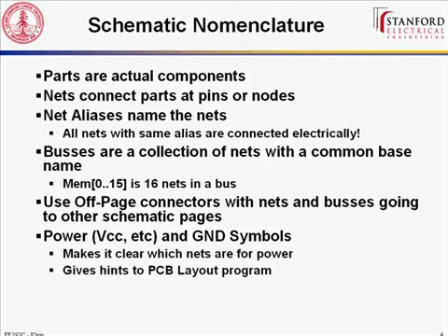For example, with a signal, you can just kind of daisy chain everything together: into one component, then out, and then into the next component, then out, and then into the third component, and out. In power, you don't necessarily want to do that, because the very last device on that daisy chain is potentially, most likely, going to have a lower voltage. So you can do different topologies like a star topology, or you can actually just have power planes. Putting these symbols on is a good visual aid for you to remember what is power, and a good hint to your layout program to help it know what is your power as well. So please do use them.